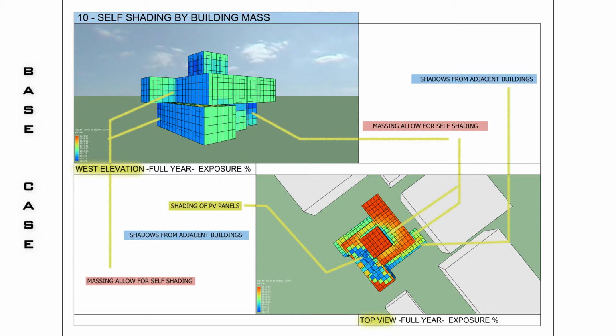Determine the optimal orientation. After we relocated the building in 8 different orientations, we selected orientation number 5, not only because it has lower energy consumption, but also because it has a self-shaded elevation toward the southwest, and because of its alignment to the adjacent road.